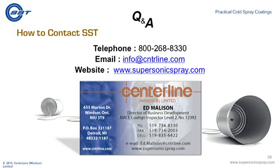Okay, good, thank you. What is the thinnest coating that can be applied? What is the metal particle size? Good. This question comes up quite a bit. Now, I want to stress to our audience members, the particle size that we start off in our raw material that we're propelling towards the surface is typically anywhere between 10 and 60 microns, depending on the material, its apparent density, etc. The size of those particles doesn't exactly correlate to the thinness of the coating that you can apply.